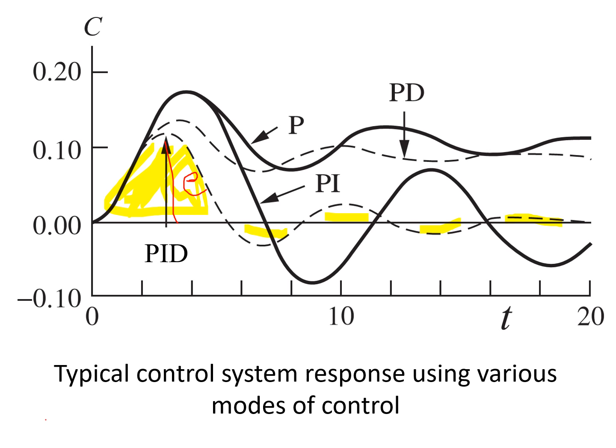And so in certain cases, you have to calculate the dynamic criteria for all the different types of controller and use these criteria to make a decision on what is the best PI controller. And also maybe different controller tunings will be used, calculate the IAE, ITAE, and then get the smallest value for your system to make the decision for what is the best controller.